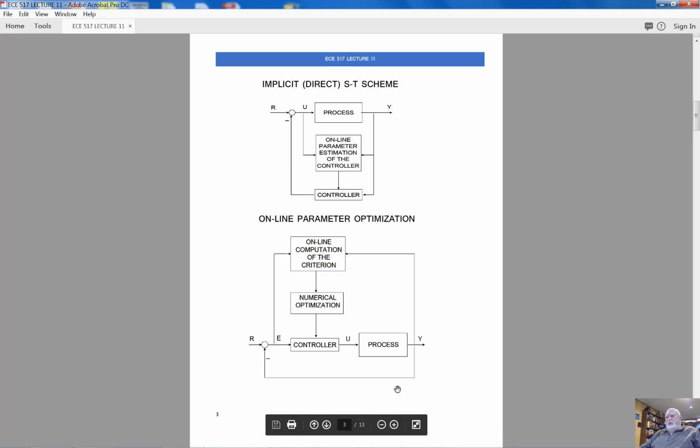But when it comes to the implicit approach, we do not have the explicit definition of matrix A, the fundamental matrix of the controlled process. We do not have the matrix B explicitly defined. What we're getting during the implicit control procedure, directly, we're getting the changed parameters of the control law.